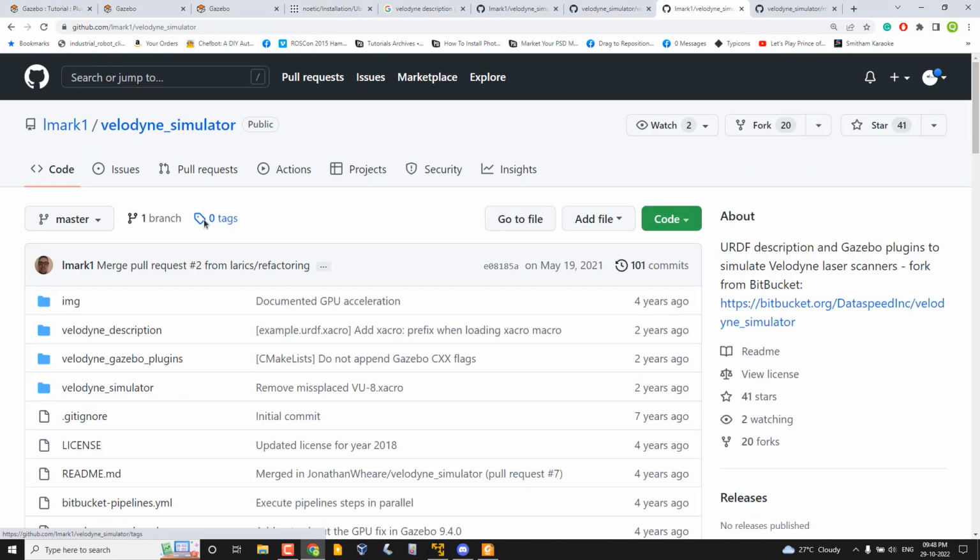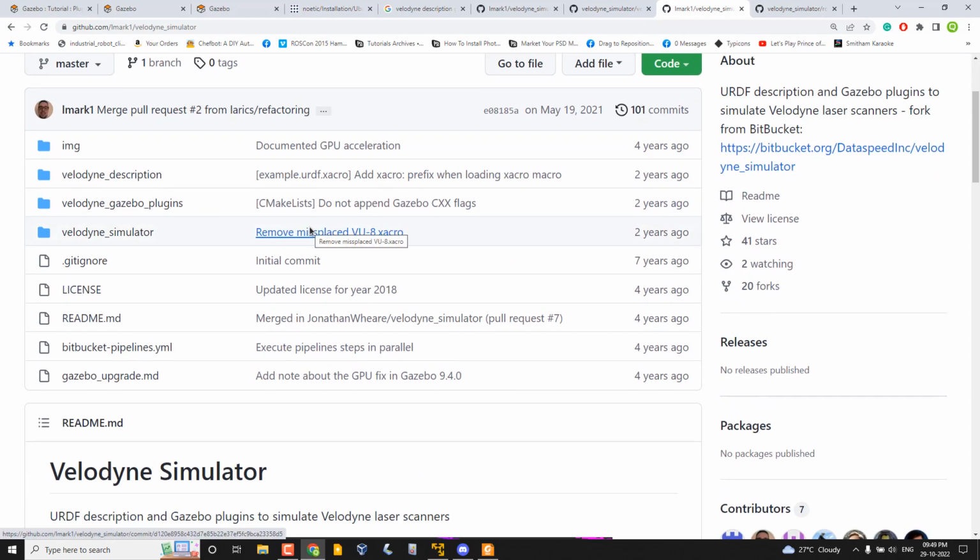Okay, so the main file when we play with Gazebo is called .world or .sdf, but you can work with ROS and Gazebo using URDF. Okay, so commonly when you work with ROS, we create a URDF file for simulation, right? So during the simulation, the URDF is internally converted into the SDF format, which is compatible with Gazebo. And whenever this conversion happens, the Gazebo plugins mentioned in the URDF are also loaded. Okay, so that's how these things work. I know it's slightly confusing, but when we start doing the plugins, you will get clarity.